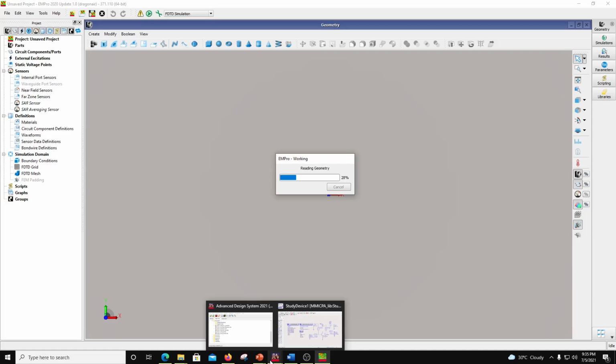When you design an IC circuit, the IC is basically the chip which is sitting inside on a QFN. The IC is not the plastic package or the ceramic package. It is the part of the wafer which is diced out, and it is wire bonded or soldered onto a pedestal. That's the chip. That's the integrated chip. And whatever you see as a plastic and pins, that's a package, right?